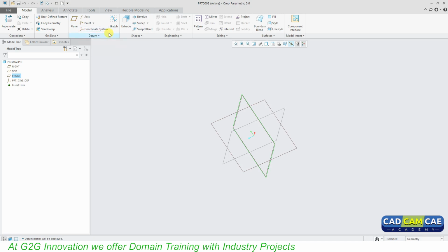Okay. Apart from this, you see there is an extrude option. So what happens in this extrude option? Let's say we have created one 2D sketch on a reference plane, and we have to create an object from that particular sketch. Then this extrude option will be used. Now let me explain how these two things will be used.